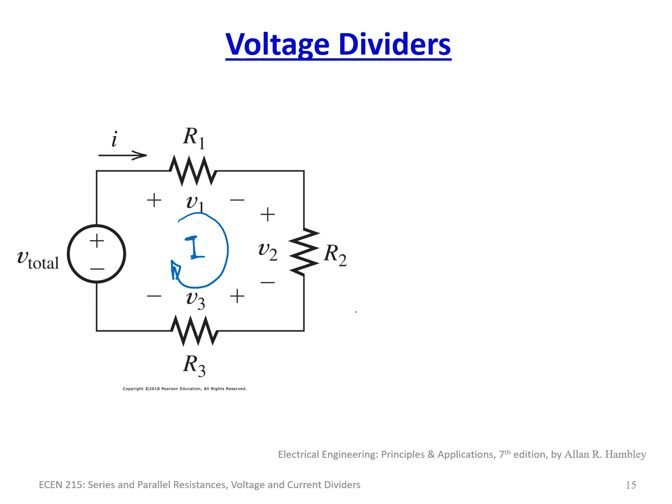So the equation, same process that we just went through a moment ago, we can now apply to this circuit. What that works out to is the voltage number 1, in other words the voltage across R1, is I times R1. And as we just discussed, I is simply equal to Vn divided by R1 plus R2 plus R3, the equivalent series resistance.